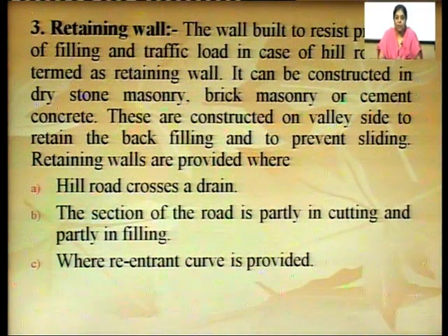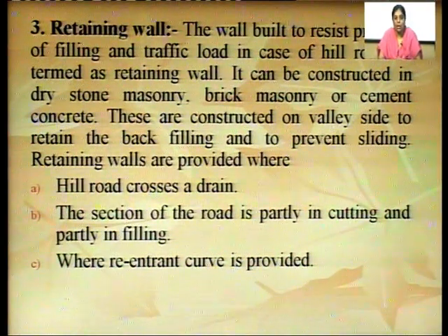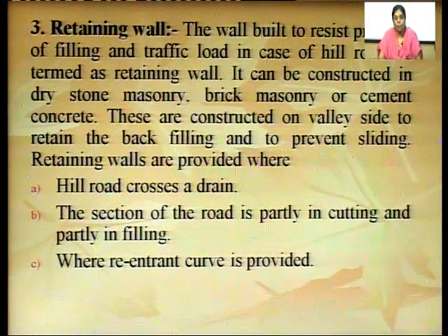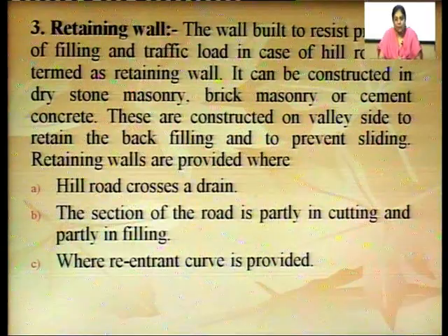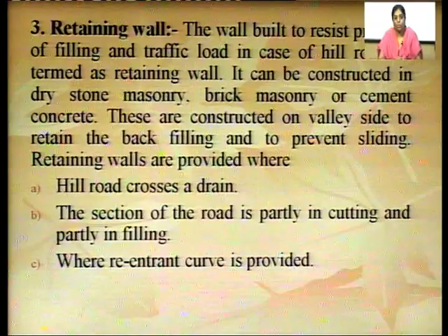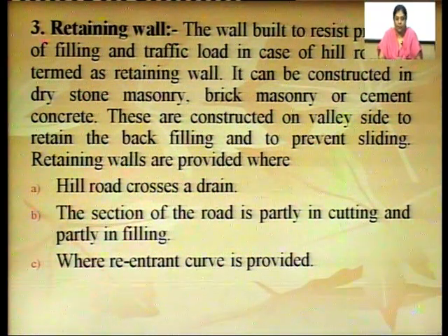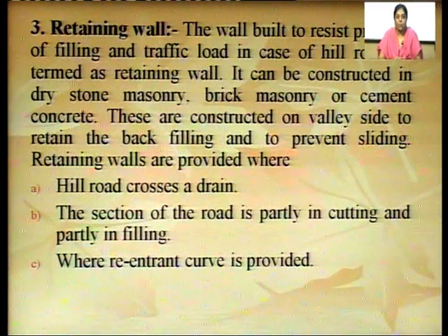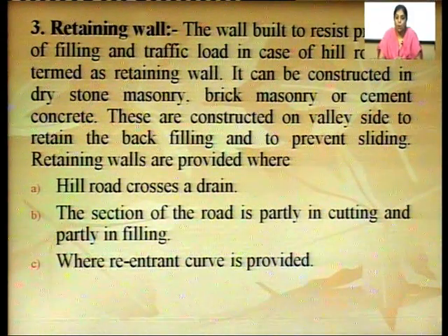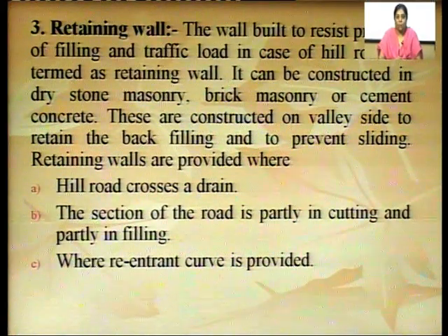And if it is constructed fully by cutting, then the retaining wall is used to retain the slope of the hill. Whenever the hill road crosses a drain, a retaining wall becomes a necessity. Also, where a re-entrant curve is provided and the slope of the hill is not very stable, a retaining wall can be built.